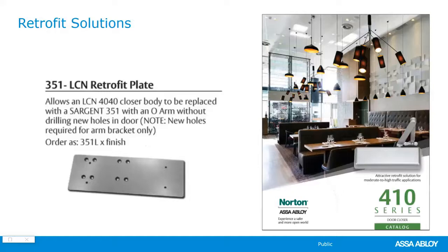Also, several of our door closer models come with retrofit plates. If you have an end user that's moving from an LCN 4040, 4050 XP model, they have a very specific bolt pattern. We have some door closers that will mount directly to that bolt pattern. And then for other door closers that don't, we sell these retrofit plates where the end user doesn't have to put any more holes in their door, making it Swiss cheese, and our door closer will mount directly to that.